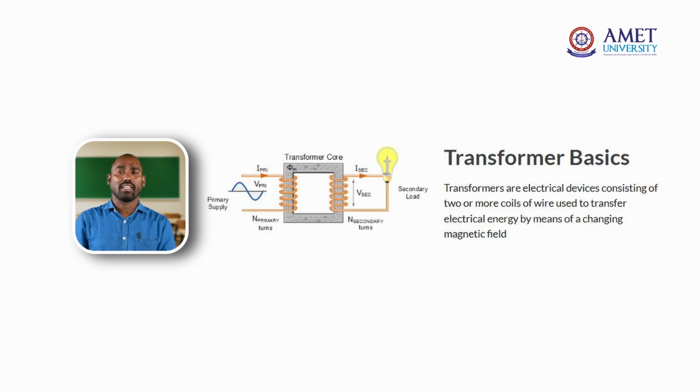What is actually happening there? We are changing the AC current from positive to negative. This continuous changing of current induces a magnetic field around the primary coil. The magnetic field created in the primary coil is transferred to the secondary coil, and this change in magnetic field in the secondary coil produces an EMF. This is the principle used in transformers.